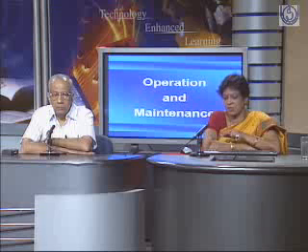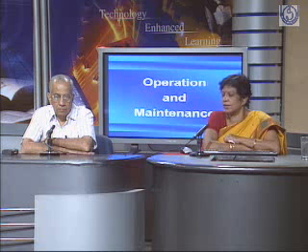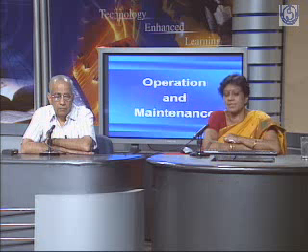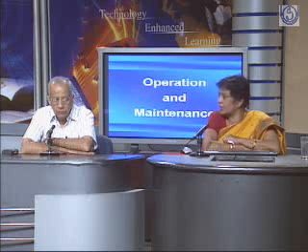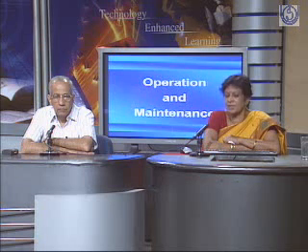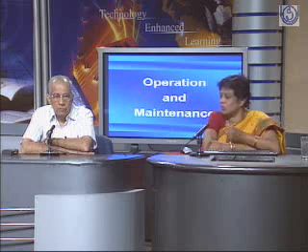It has been observed that 65% of the failures are due to failure of the LV coil. And the LV coil fails mostly due to failure in the LT system, due to overloading and things like this. So when we use HVDS, we do not overload the system because there are 3 or 4 customers only on that transformer, and they themselves see that there is no hooking. Overloading is mainly caused by hooking, and if there is no hooking, then there will be no overloading. So the transformers are less likely to fail.